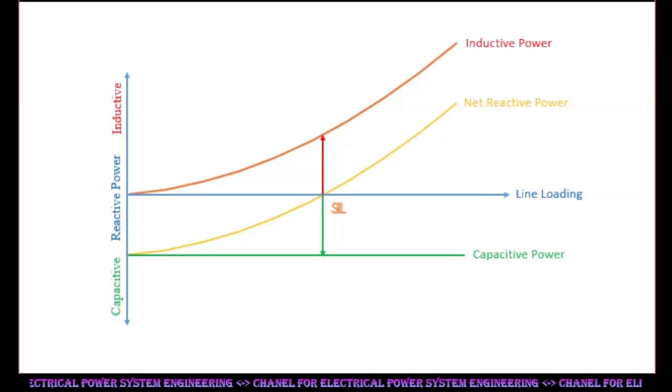But the load on the lines depends on locations of power sources, locations of load centers and parallel paths in the system network. So it is impractical to operate all the lines all the time at load close to SIL. However, there is an alternate way to achieve the target: modifying the SIL level of the line to match the load on the line.